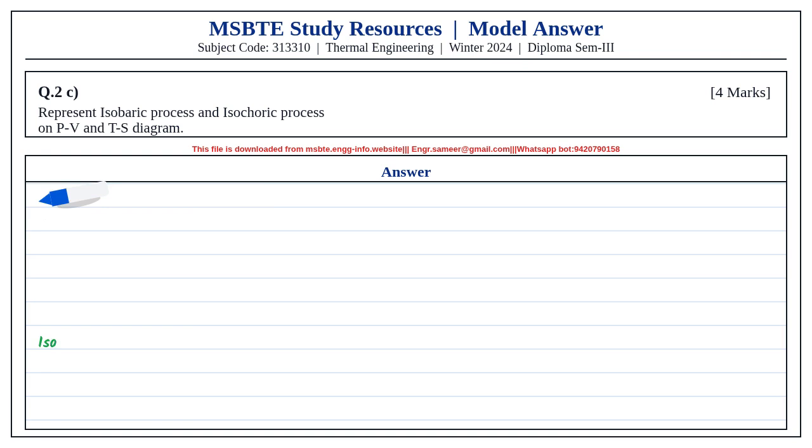Question 3b. Explain construction and working of surface condenser with neat sketch. The figure shows a surface condenser. It consists of an airtight cylindrical shell with a large number of water tubes fixed between tube plates. Baffle plates guide the steam flow.